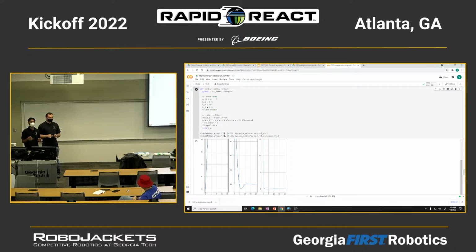The elevator has some weight, and so the motor will always have to hold that weight up. And with a P controller alone, there will be situations where the force applied by the P controller is equal to gravity. So there's a stable point that may not necessarily be at your goal location. So adding the I term in that situation will allow you to overcome gravity and position the elevator wherever you want.